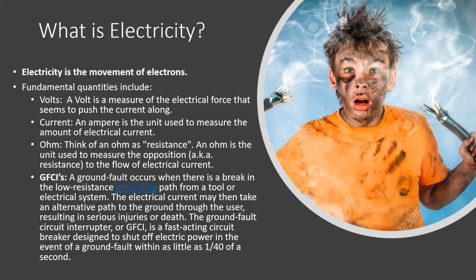The purpose of this GFCI device is basically, whenever there is any fault in the grounding, for example if the input is not equal to output due to grounding issues, this device is going to be initiated with very high speed, which is 1/40 of a second. So this is going to disconnect our source of electricity and the socket, so our device is going to be safe.